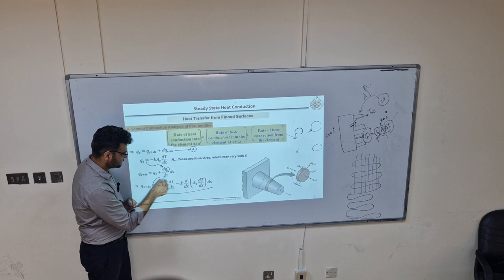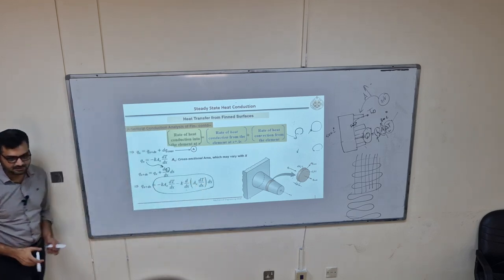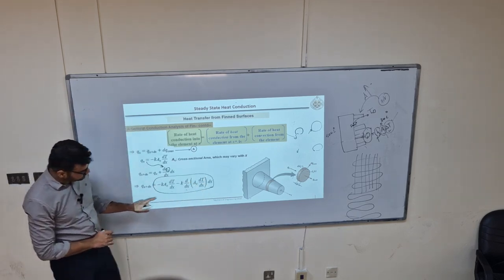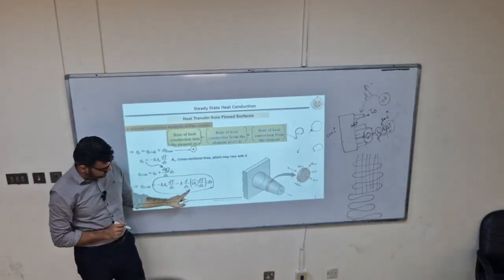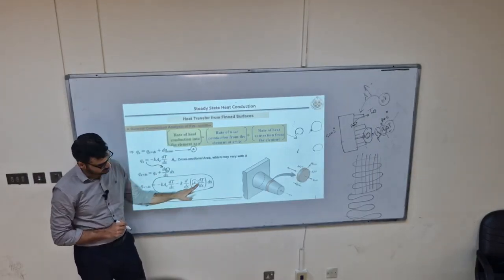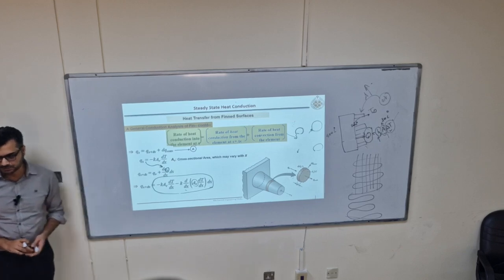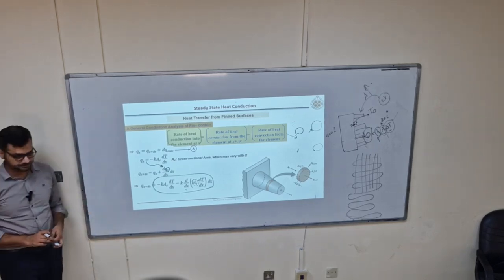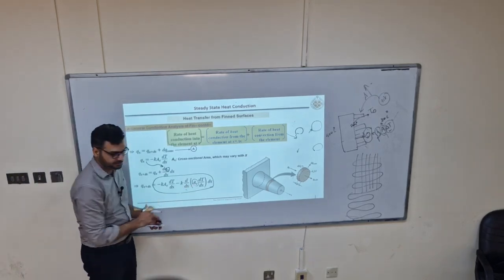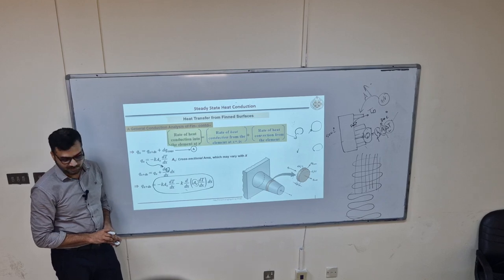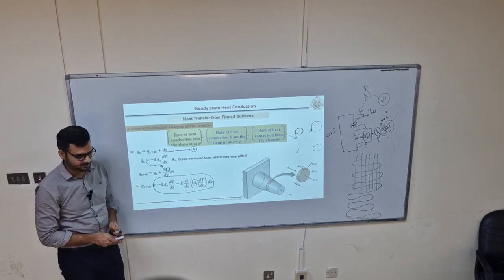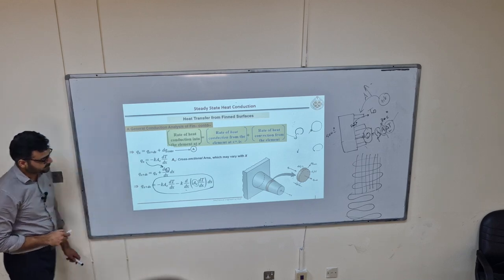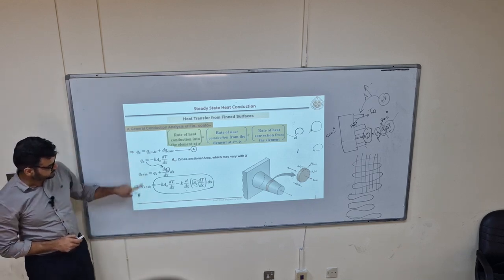Okay, now it makes things interesting. Look here. What about the cross-sectional area for that fin which is shown? Is it changing with respect to x or not? Yes. So Ac is not constant. Ac is changing with respect to x. We will assume it constant later on, otherwise it will be very difficult to solve at this point. Okay, so Qx plus dx is clear.